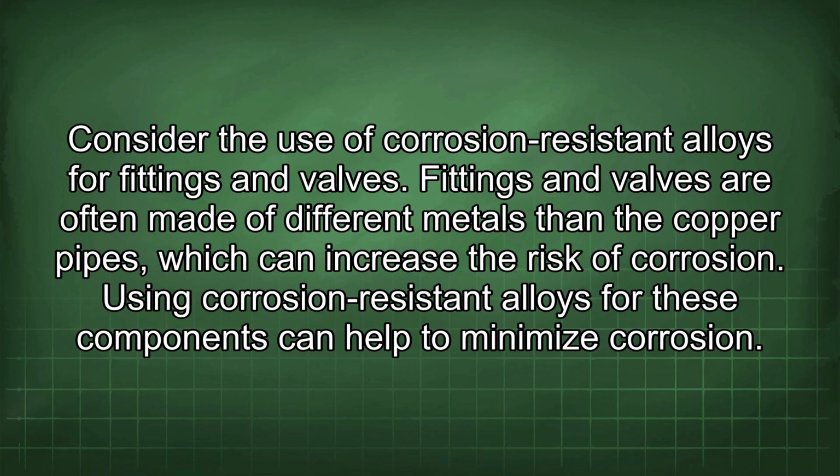Consider the use of corrosion-resistant alloys for fittings and valves. Fittings and valves are often made of different metals than the copper pipes, which can increase the risk of corrosion. Using corrosion-resistant alloys for these components can help to minimize corrosion.